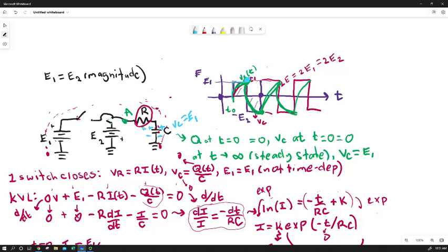Now what happens when we close this switch? Because that's the condition we get on this portion of the square wave, which is what we can measure on our scope. What happens when we now, instead of just going back to a voltage of 0, we double down? Because now, if you think about it, you've effectively got E2 and C that are pushing in the same direction, and current is going to want to flow this way until they've discharged, but they have to flow through the resistor, and they're flowing in the opposite direction now.